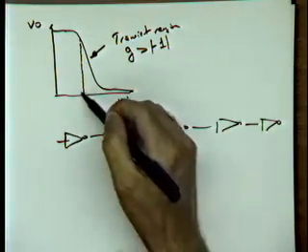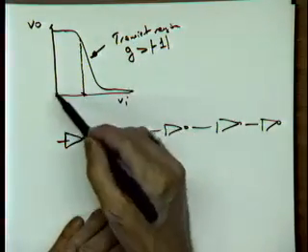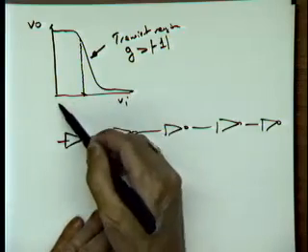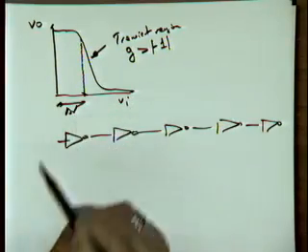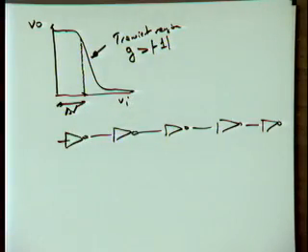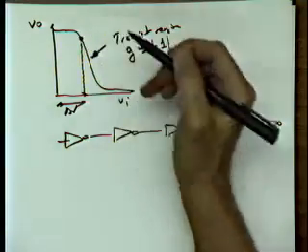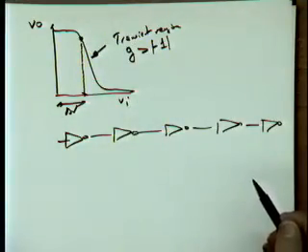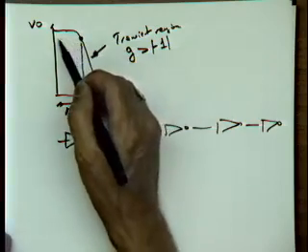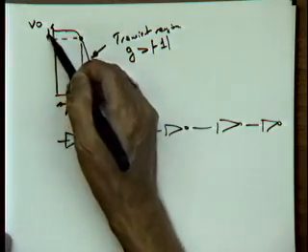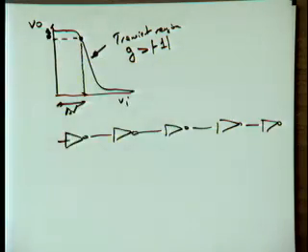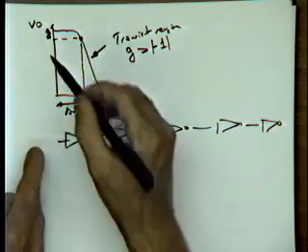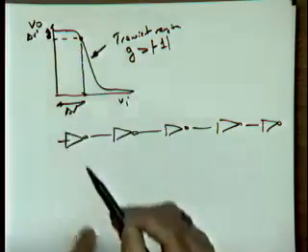Normally we would like to see the input be perfectly 0, but there was some noise added which was delta V. So you can see that the output of this gate is not going to be perfect. But what you observe is that because I have gain here, while I have delta V here, delta V prime at the output is going to be smaller.